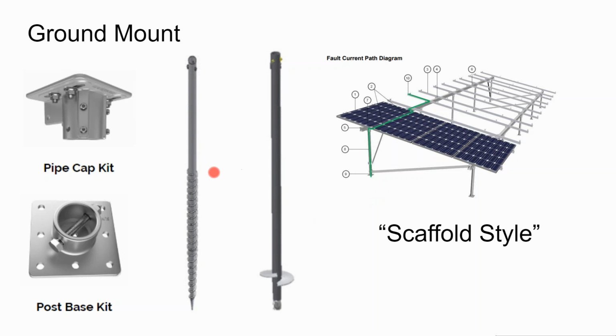So I recently started to look into ground screws and earth screws. And they went in pretty well. You have to hand guide them because when they're initially going in, they kind of want to turn out of place and jump out of position. You kind of have to hand guide them into place.